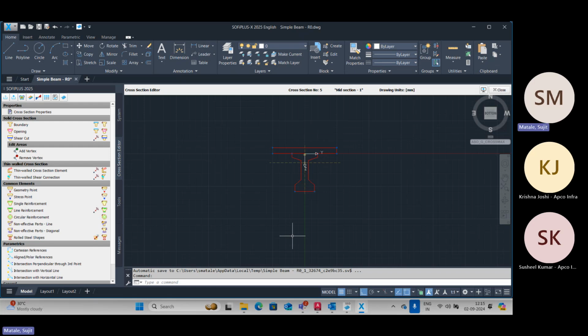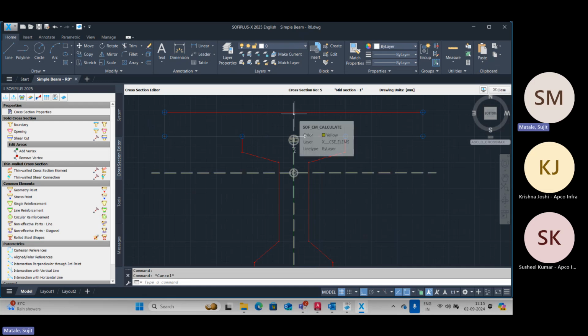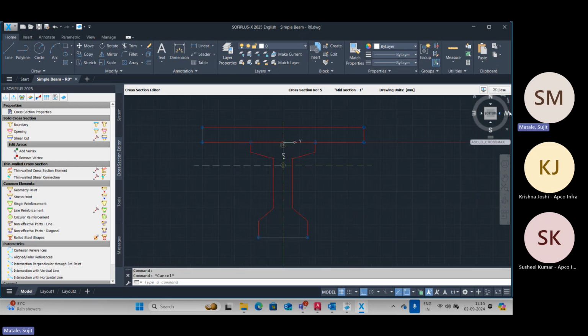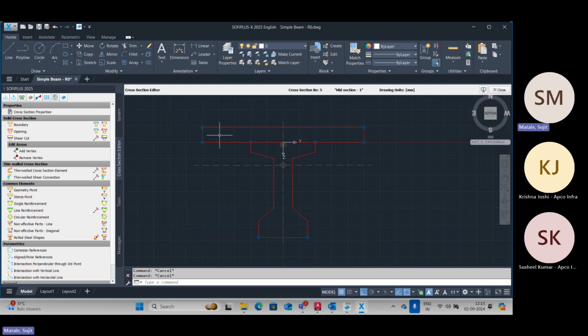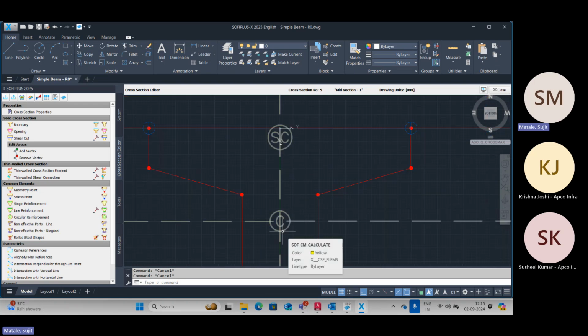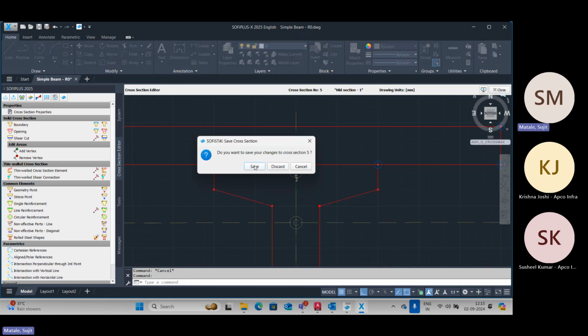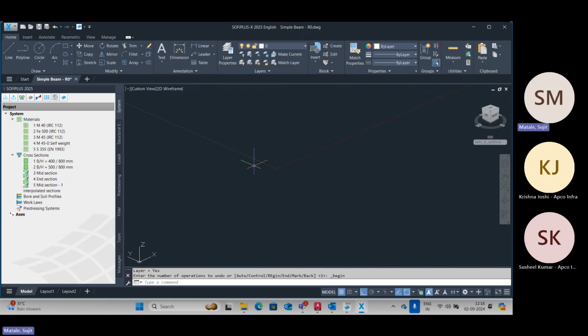So what I now do further is, just for your information, I can delete these stress points or define my stress points, let's say at slab top, girder bottom, my points of interest anywhere in the cross section. You don't do it now. So I hope you could all analyze this cross section as well, right? And if you press F2, you should get these numbers. Okay. So the moment you get these stress points defined and you get this shear center here and centroid over here, that means your cross section is assigned. So I just close this down because your first cross section is defined.